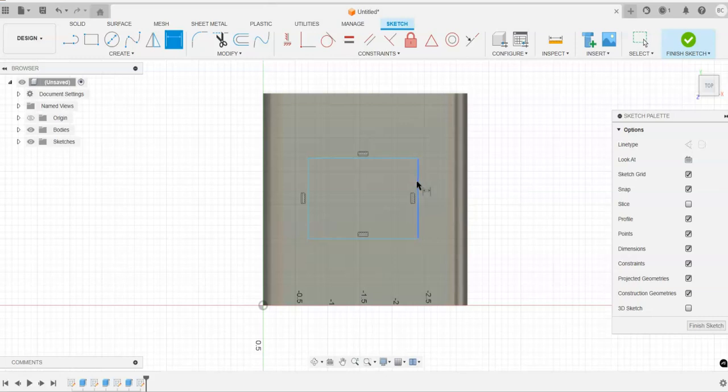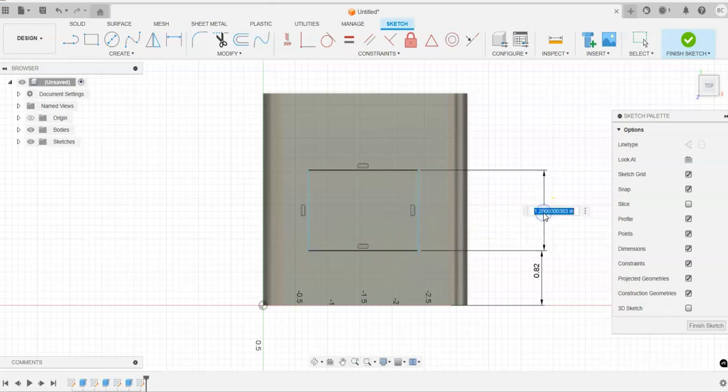In this case, we are coming from this front edge to here is going to be 0.82. So that's 0.82, and then we have another 1.59. So if I go with this line, we're going to go 1.59. All right, now notice how both of these lines went along with each other because they are kind of constrained together when we created a rectangle. If we used the line drawing tool, they may or may not have been constrained that way. So just some of the other differences that you may get as you're looking at this and doing this.